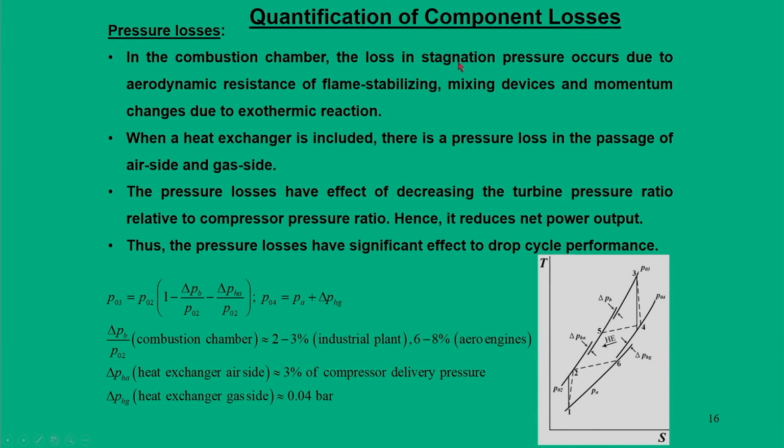Now, let us see how you are going to calculate the component losses, and it is a pressure loss. We have talked about compressor and turbine. Let us see what happens to pressure losses in the heat exchanger. In fact, the heat exchanger is also an important component, and these heat exchanger component losses are taken into account through pressure losses. So, what happens? When a heat exchanger is incorporated, the main intention is to tap the heat from the turbine exhaust and to preheat.